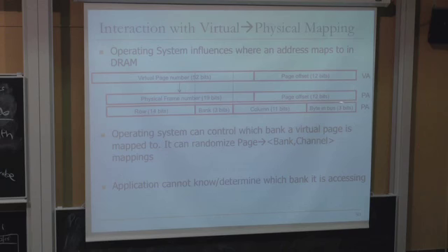Now, if you look at the physical address from a different point of view, which is the point of view of the memory controller, basically, the memory controller takes these 11 bits as a column address and takes these 3 bits as a bank address. And look, these 3 bits are affected by the translation process, right? And these 14 bits are also affected by the translation process.